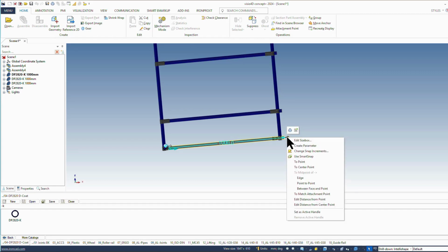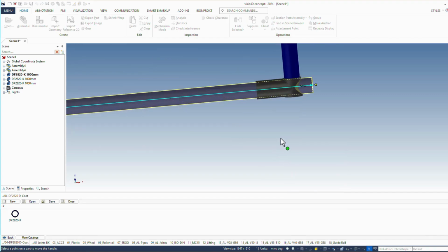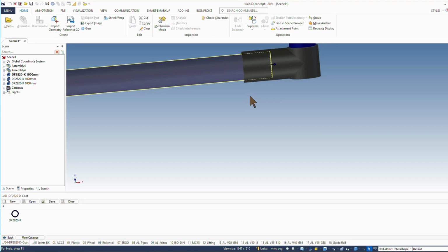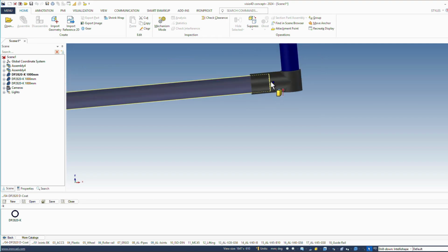Here, I can now right-click and select 2 point, and then I have the length. And then I could now say, I'll use the arrow key to move the cursor to the right and type +30. Then I'll have the length entered. Another way would be that I press the Alt key to jump straight to the pipe. Then I'm always taken straight to the point of change in length on the pipe.